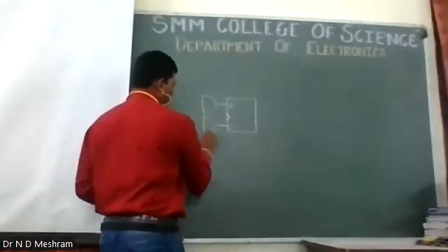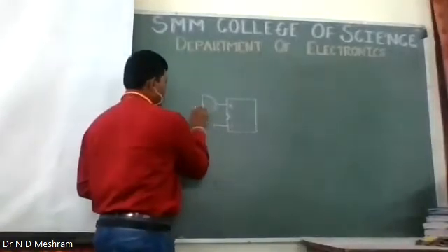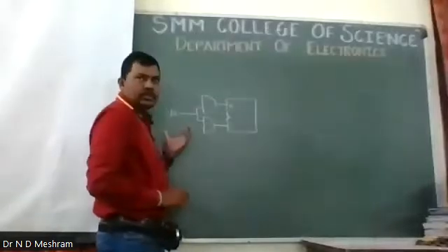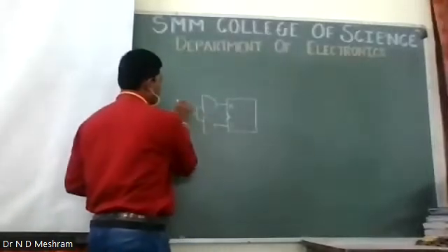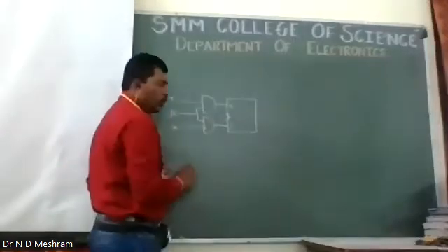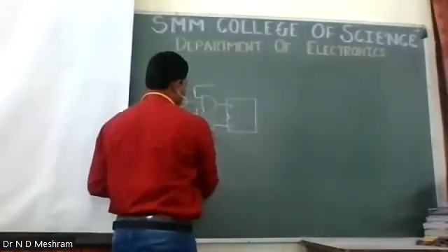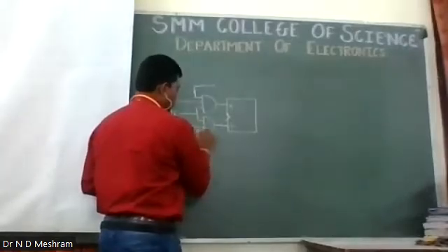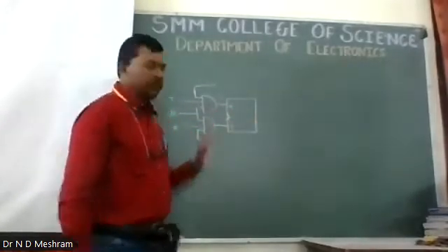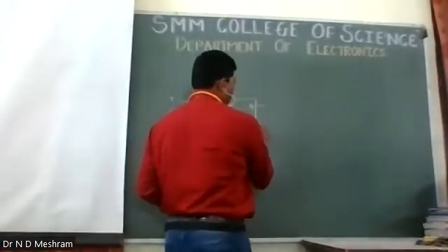So we will be having two AND gates with three inputs like this, and the first input is given to the clock of the circuit, and the second input is J and K, okay, and the third input is the feedback. So I will keep it floating right now, and after that we will connect this. So this is the first JK flip flop. The second flip flop is the same, so we'll have Q and Q bar like this.